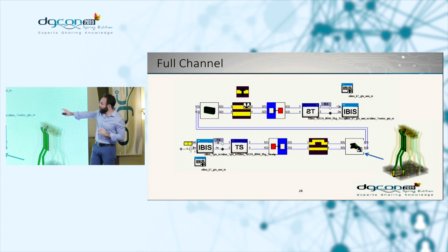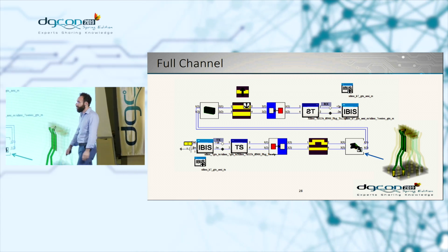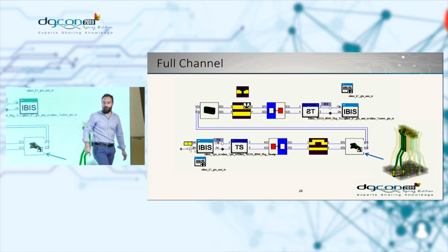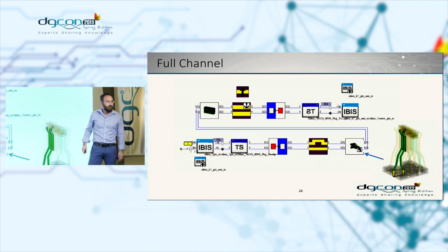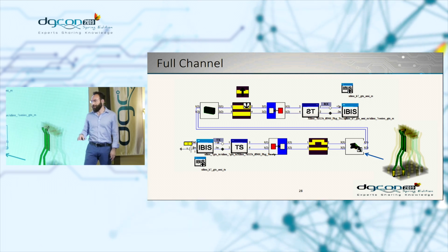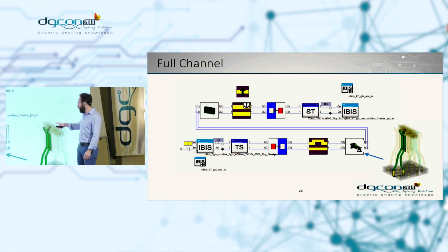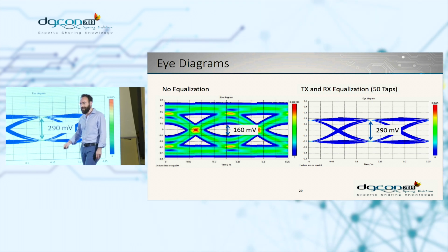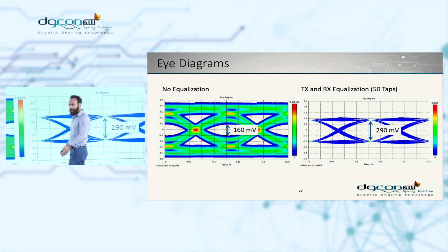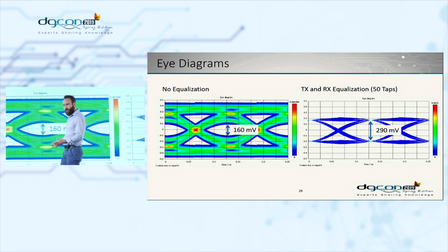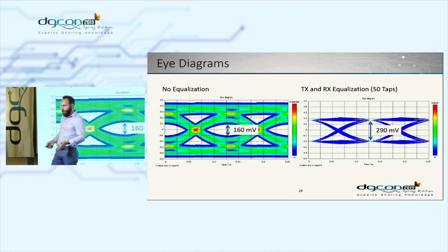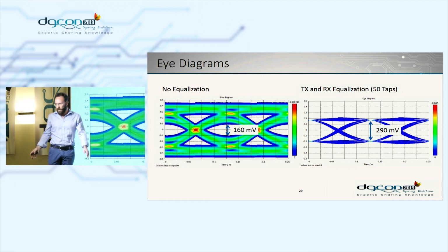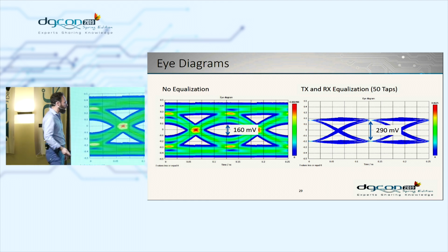And the full picture is something like that. Connectors, IBIS file, some transition, some vias. This is the full picture. And at the end of the story, we are able to evaluate the eye diagram taking care about all the transition that we have. What we can do at this point? We can proceed with the prototyping, with the mass production, or whatever you want, if we are lucky.